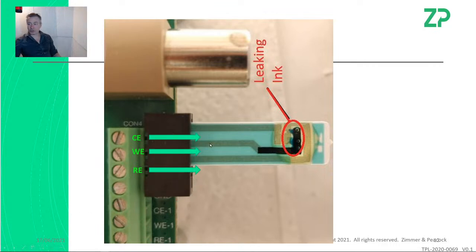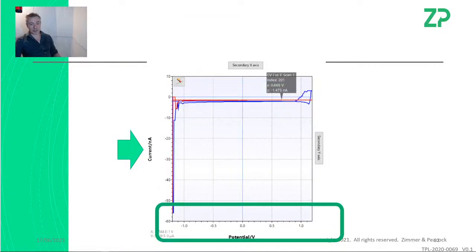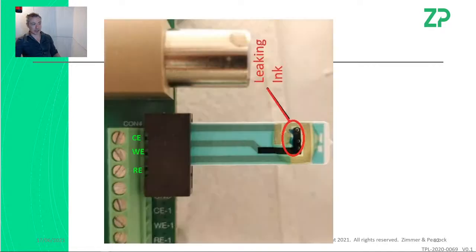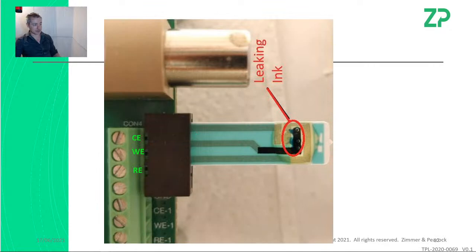Essentially this piece has not been aligned in the connector correctly, so it's literally not in contact. When you get signals flatline like that, the biggest reason is generally misalignment.